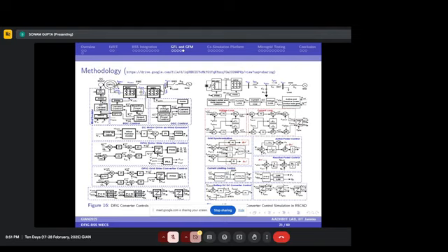From the stator side, it is directly connected to the grid, and from the rotor side, there are two converters. Here the conventional vector controls are implemented on the rotor side and grid side converters. For the DFIG rotor side converter, we can see two loops, for the active and reactive power; the rotor side converter control is basically for controlling the speed and the reactive power as well.